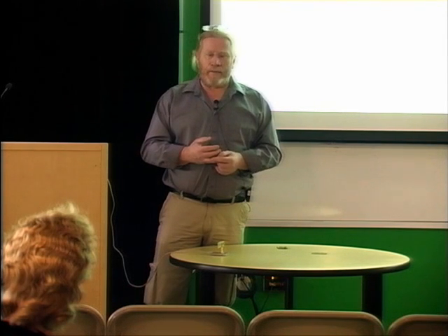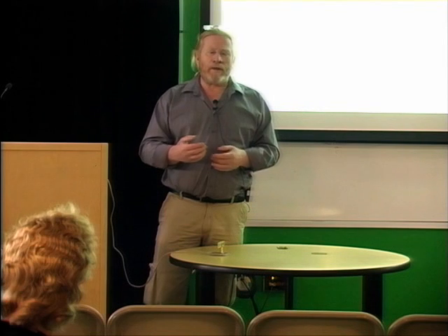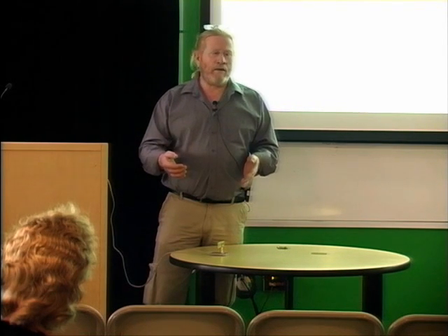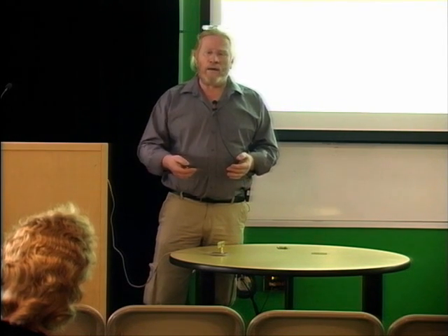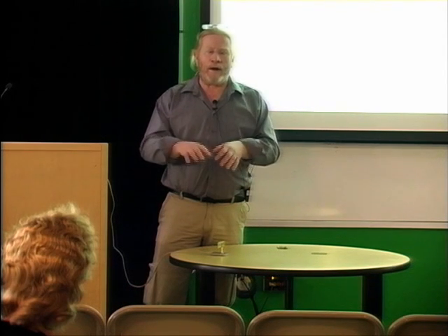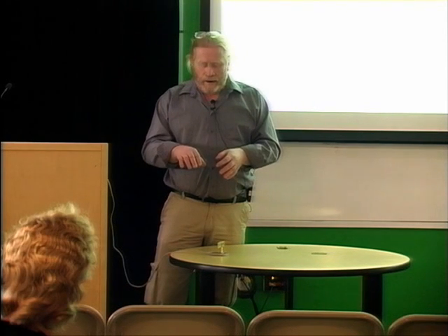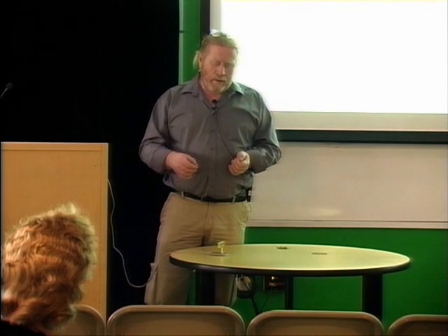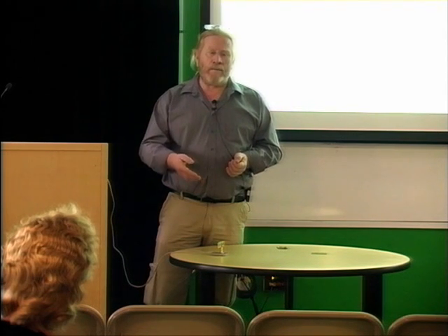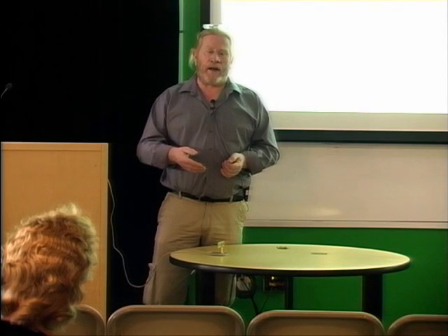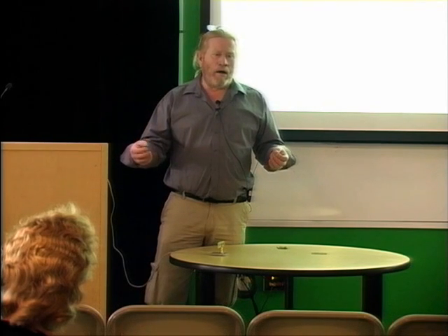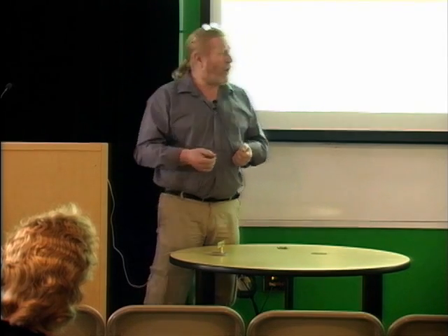There's no magic to this. The only thing we're doing is integrating. We are sending not only one pulse, but millions of pulses, right? If you keep doing that for a while, you are able to reduce your white noise by integration. So there's no magic to it. The important thing from this example is that our implementation enables us to make these kinds of long integrations, which used to be a problem with standard analog integrators because they are lossy. But I'll explain that.